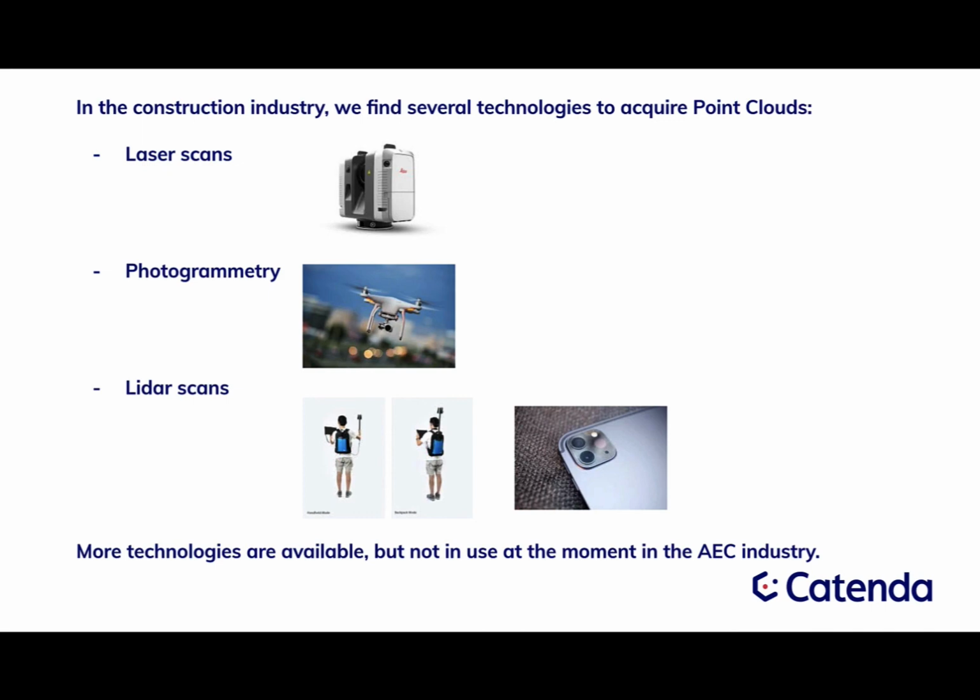And you may not know, but you may already have a device with this capability in your pocket or on your desk, because the latest releases, I think the iPhone 12 Pro, the Pro versions of iPhones and iPads, have a LIDAR sensor embedded. So you can already do this, and I will show you a little demo at the end of this presentation on how you can use it nowadays with some apps and upload the result to Bimsync. There are more technologies available on the market, but they are not used right now in the construction industry. There are touch sensors, where you have to follow the surface of a part with specific devices, and that's not really on the market for the AECOO industry nowadays.